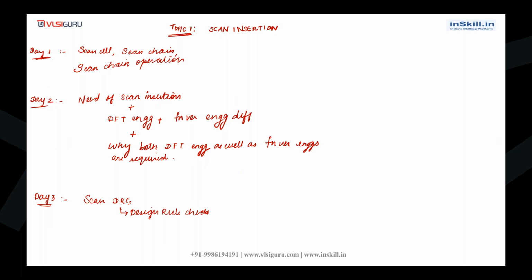So what is scan insertion? Scan insertion means all the normal flops have to be converted into scan flops, and yes, the scan flops will be stitched into a scan chain. Yes, correct. But if it has to be converted to a scan flop, then it has to pass certain rules. Now, what are those rules? That is nothing but your DRCs.